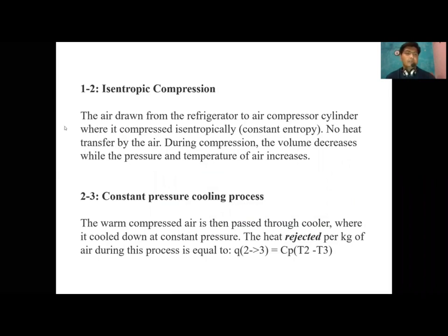First is isentropic compression. The air is drawn from the refrigerator to the air compressor cylinder, where it is compressed isentropically. No heat is transferred by the air during compression. The volume decreases while the pressure and temperature increase.